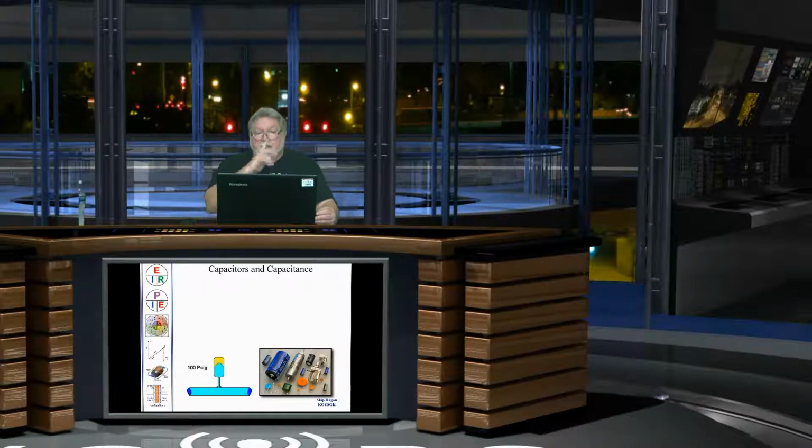So the people who provide those filters put in this accumulator, and when you're not using water, the water slowly comes through the filters and into the accumulator until the water pressure inside the accumulator is balanced with the water supply to the filters.